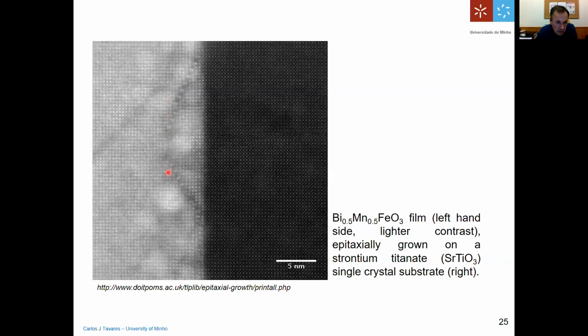Here you can see some kind of shadowing effects on this micrograph. There can be some defects here. So you have some faults here. For example, there are some atoms missing here, if you take a closer look. And also on these shaded parts, maybe you'll find some defects, the stacking faults, or you can have some holes, which means that the atoms which were supposed to be there are not. Or you can have some interstitial atoms.